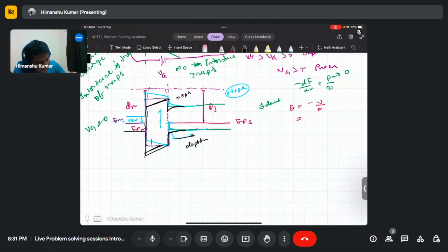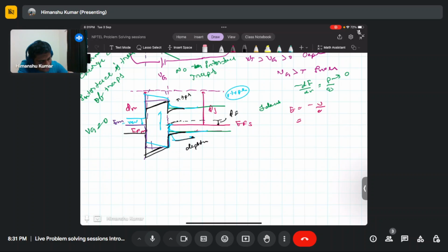Now this is the surface potential phi f, and if you apply a bias, then the banding will follow a similar trend. If you keep increasing the gate bias, more and more banding will be there. After a certain threshold, this bending will become 2 times phi f, that is psi s will become 2 times psi f, and that is known as the boundary of the inversion layer.